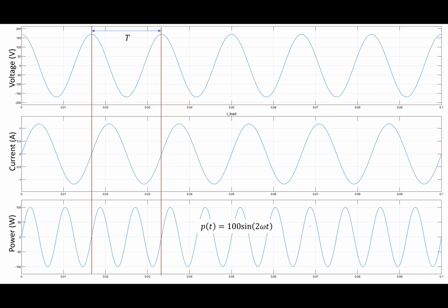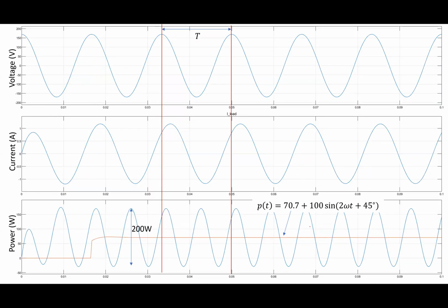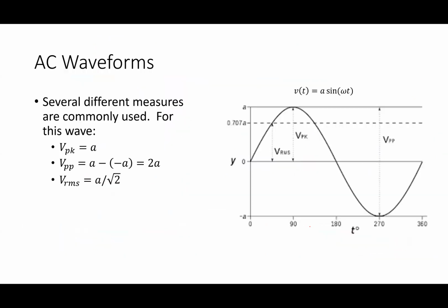For the other half of the cycle, it's flowing out. Basically it's storing and then sourcing, storing and then sourcing, and on average, it's doing nothing. There's no energy conversion happening. It's just storing, but there is still a current that flows through the wires to make that energy storage happen. I'm not going to get too into the weeds on that. For this guy, it would be somewhere in between if it's an R and an L. You can look at that stuff later.